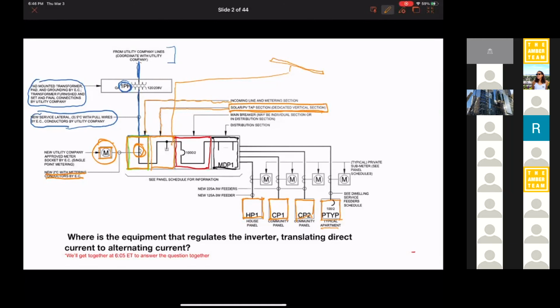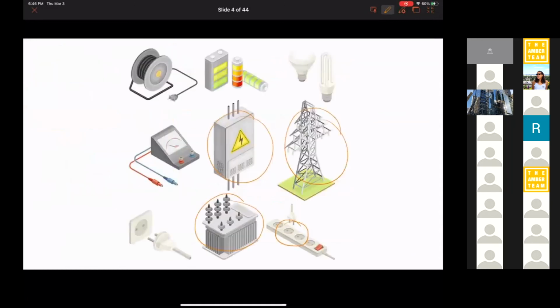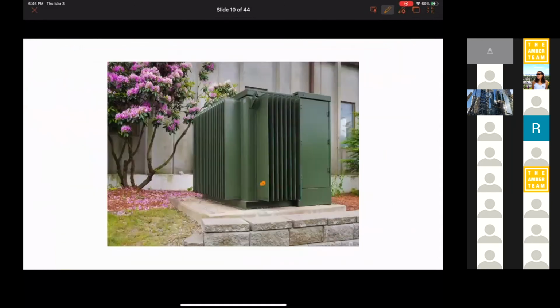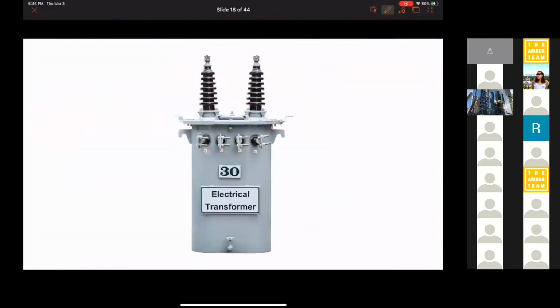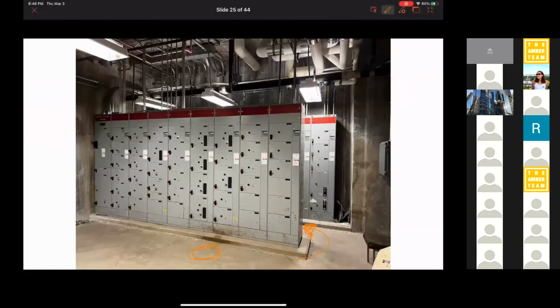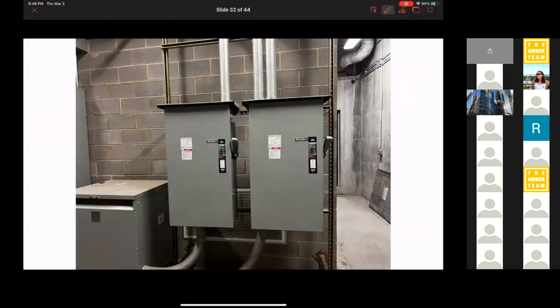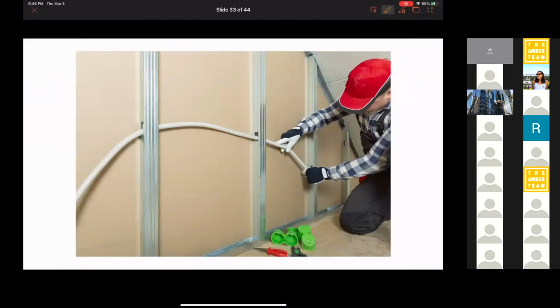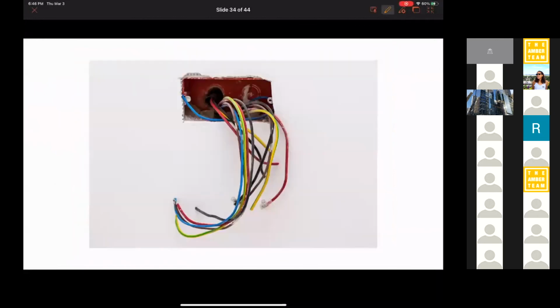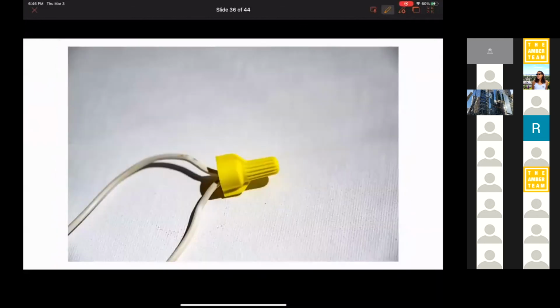It's going to take in the line from the photovoltaics and give us a place where if we ever replace the photovoltaics or add more, we'll have a panel instead of busting open a wall and trying to figure out what's going on. So what these panels are trying to solve for is we don't want a situation like this, where we have all these connections in the wall and just use wire nuts to do that kind of thing.